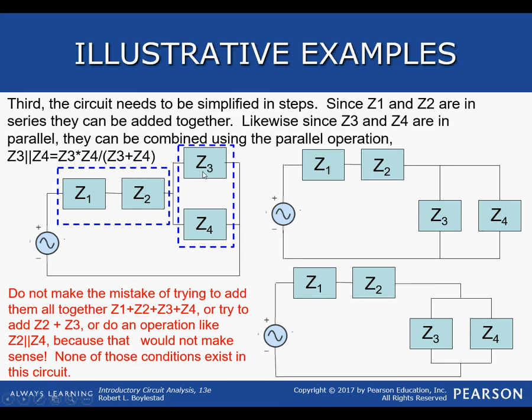In a rectangular fashion, it'll be R plus jX, or in polar, it will be Z with an angle of theta. But whatever way you do it, your calculator should be able to handle either way, and you don't have to flip between modes unless you're asked to give a number in the other form.